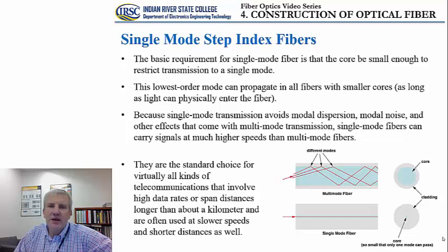So in this case, modal dispersion is completely removed, since we have just a single mode, and since single mode transmission avoids modal dispersion, modal noise, and other effects that come with multi-mode transmission, they will not be present in this type of structure. An immediate effect is that these types of fibers can carry signals at much higher speeds than multi-mode fibers.